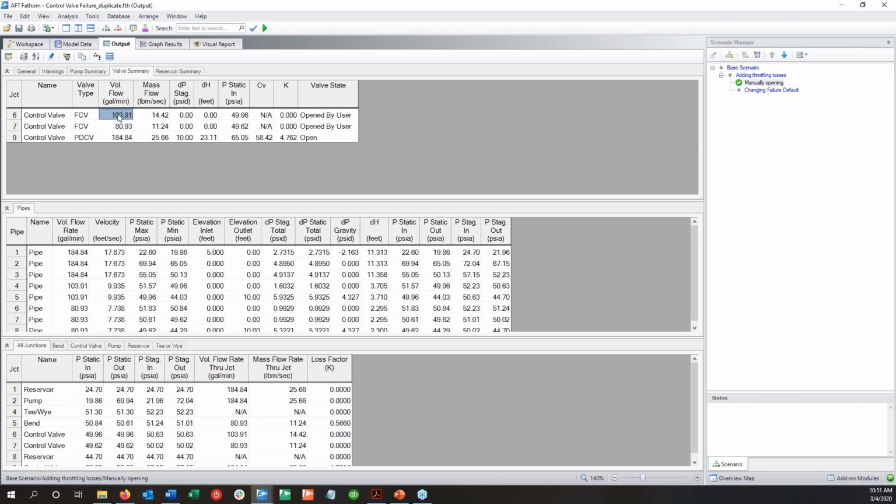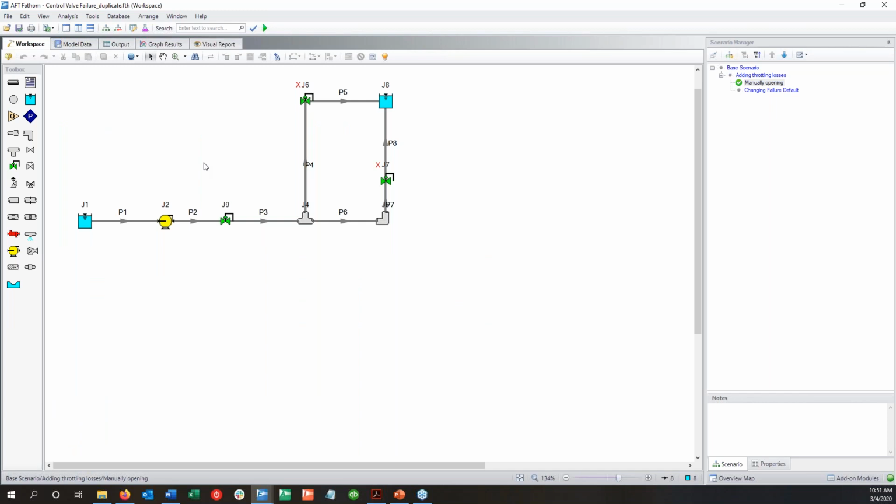So the question is, what gives? Why is this flow able to be controlled, but when we ran both control valves, they failed? The issue is that both of them were always controlling, so you would assume some flow rate through here, and you're also assuming some flow rate through here. The additional flow rate through here probably causes a pressure drop that permeates to here, and then you get insufficient flow at both of them because they're all assigning that flow at the same time.